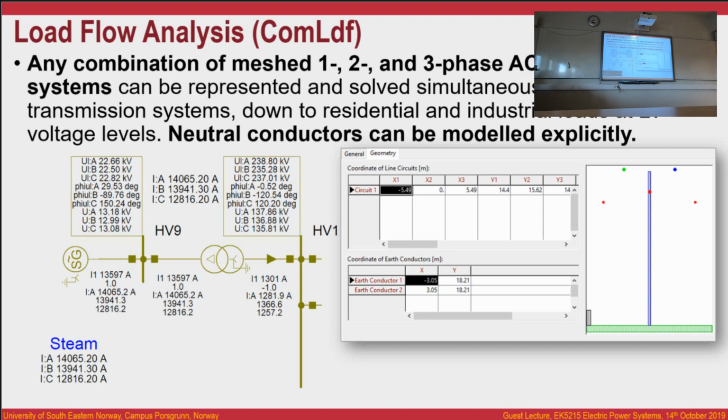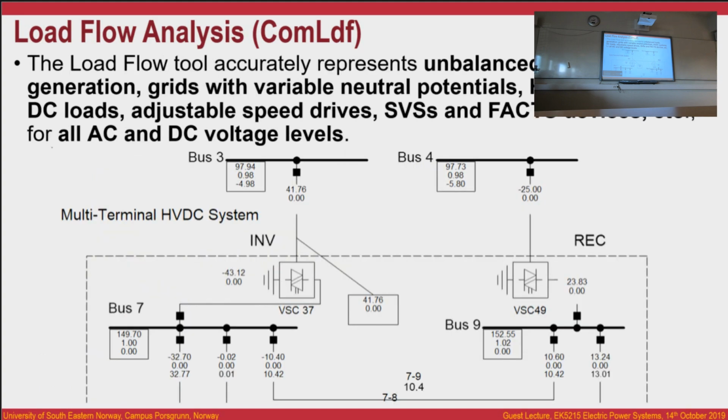To be honest, power flow, I solved the power flow over there using just a 3-phase system. And I say you need to use this equation, the power balance. And because the system is a 3-phase and balanced system, you say the 3 phases are using the same power. But in distribution system, you can have phase A loaded more than phase B or phase C. PowerFactory has the possibility of calculating single phase, double phase, or 3-phase load flow. And this is beautiful.